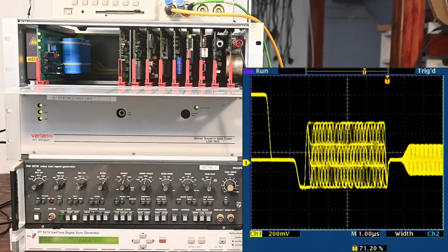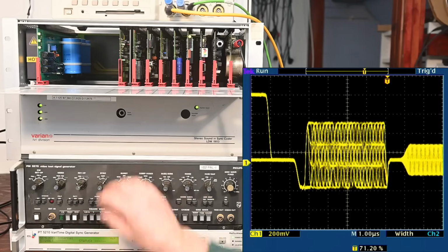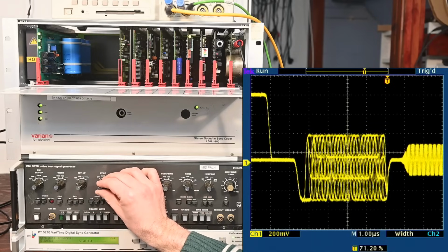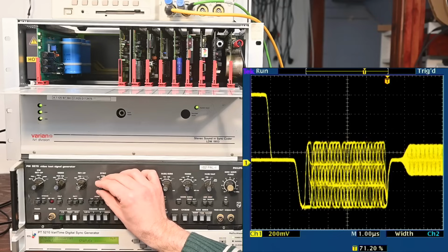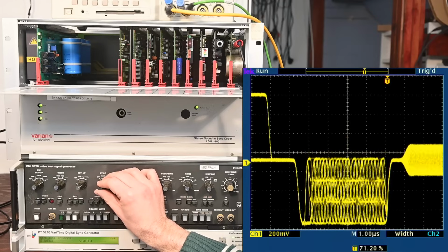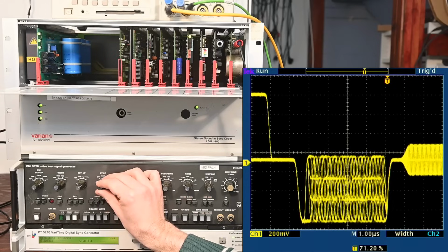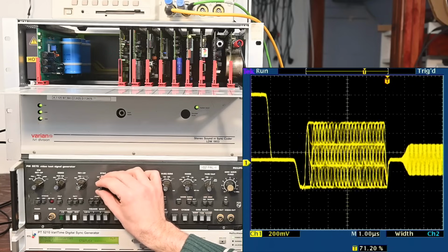Now let's get testing. Now the first one I want to do is the sync. We do have the ability to stretch the sync here. And let's just drag this down and see what impact this has on it. Oh dear. Oh, that's nasty. Quite a nasty sound that made on the way here, but yeah, if I stretch the sync far enough, it dies altogether. I'm quite surprised to see that, actually. I would have thought the ADC would be AC coupled, but yeah, the DC level of the sync definitely has a considerable impact on it, so not something you want to get wrong. So we'll set that back to the correct level.